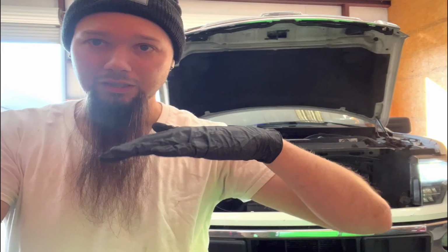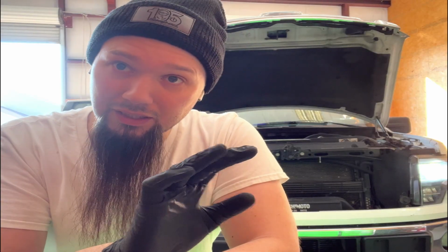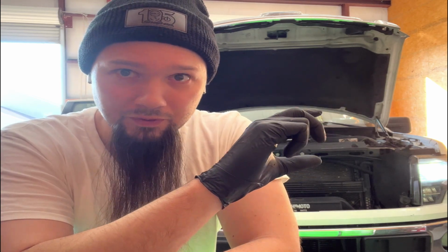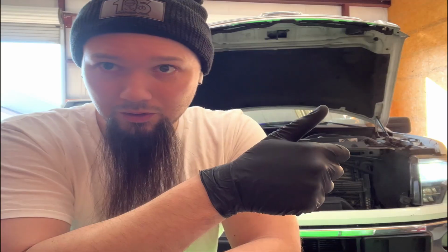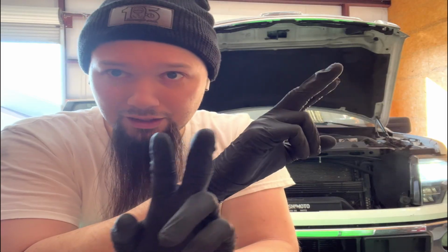Say 180 is two wheel, and 180 is a 4 low or something like that, somewhere in between, as it makes that sweep, the switches will change. So I was going to do a screen record of doing a clockwise, counterclockwise with the scan tool and see if any combinations thereof match the table. And perhaps we're just driving that motor to its full clockwise or full counterclockwise position. And if that would have been the case, perhaps it's just not a normally operable position that it could be in. And in getting ready to do that test, I have a new result that we have not seen before,